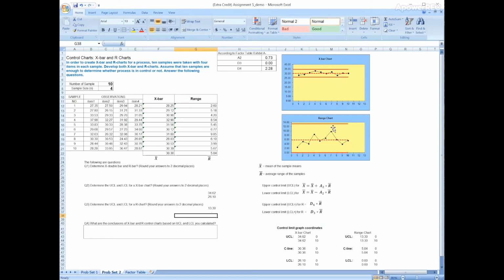We notice that all of the sample data points plotted on these two charts fall within the red lines UCL and LCL. Based on these observations, it is clear that the process for manufacturing these 4 items is in statistical control within the 3 sigma confidence interval, despite there being some of the samples with the length below the center line, the average in the X bar chart. I hope you better understand quality control from this exercise. That's it.